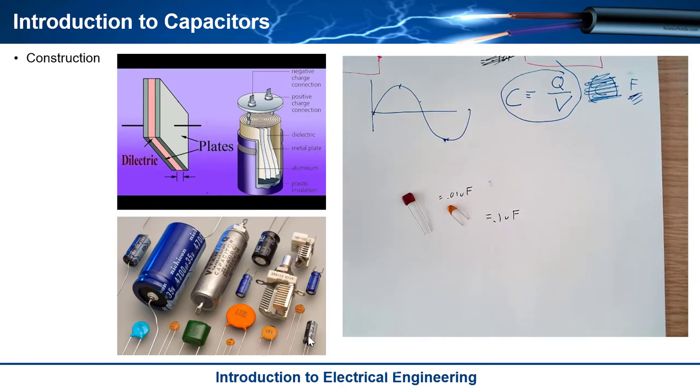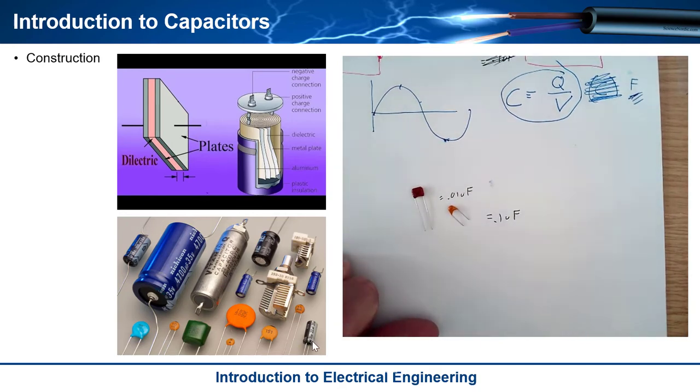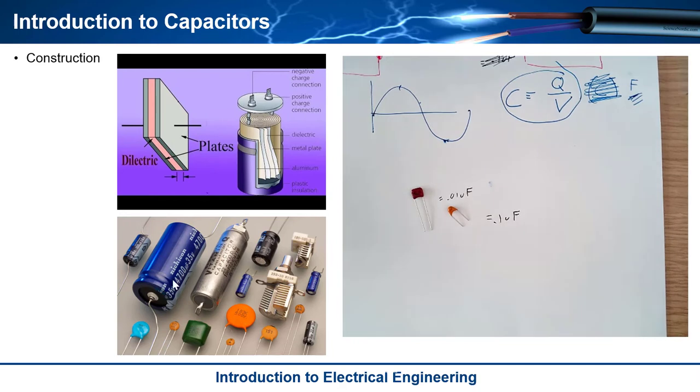So here's a can, or a cylindrical capacitor, and it's about the same size as this one right here. You can see the value on it. It's big enough that you can write on the side of it, and this is 22 microfarads. This bigger can right here is what you typically see when you open up a computer motherboard, and that one's 4,700 microfarads. That's 4.7 millifarads.